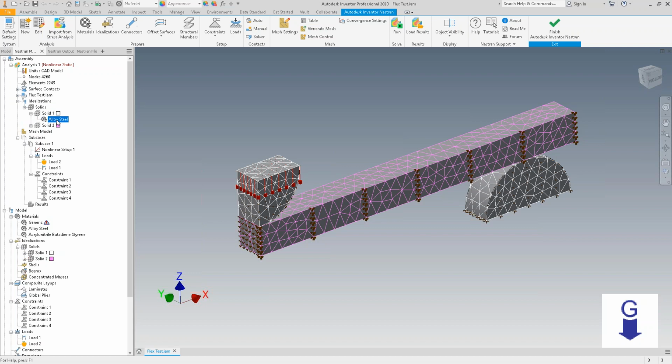From my own past experience, I know that we poured ductile iron at a different density than what all of your material libraries called out. We also had slightly different Young's modulus calculations than what all the libraries called out. So you've got to get those right. Nonlinear materials, it's a huge ball game in that area.